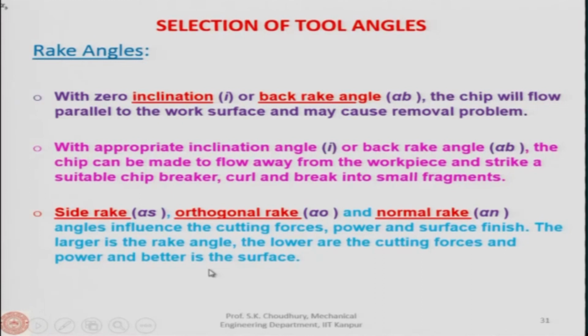Precisely what we say, I showed it to you last time probably, is that if it is the cutting force, for example, and if it is alpha, which is one of them, it goes like this, meaning that as alpha increases, Fc decreases. We always want the cutting force to decrease, because the power P is equal to Fc times Vc. So if we can reduce Fc, Vc being constant, the power is reduced.